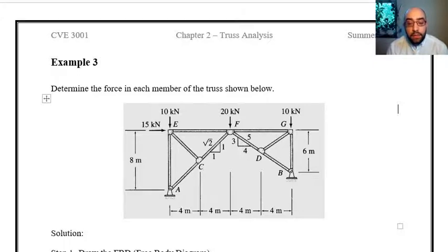That's fine. But we have to make sure we include the right sign for the members in our calculations. We are not supposed to change our initial guess in terms of the forces at the joints, but we have to include the sign of the members that we obtain during the calculations in our future calculations about the truss. You will see how it works in this example, and you saw it in the previous examples that I solved in this file.